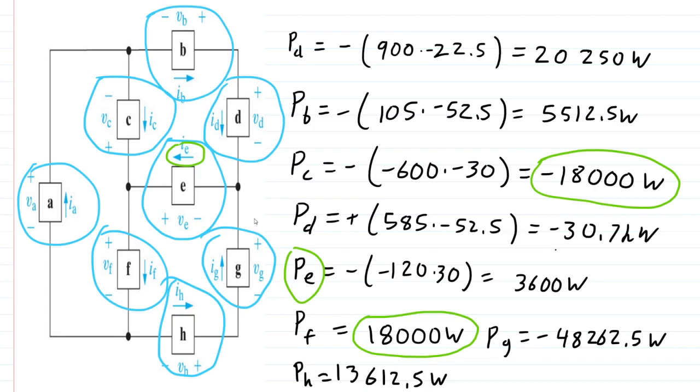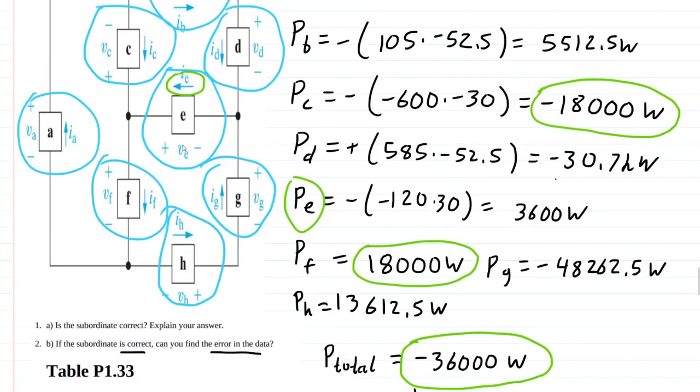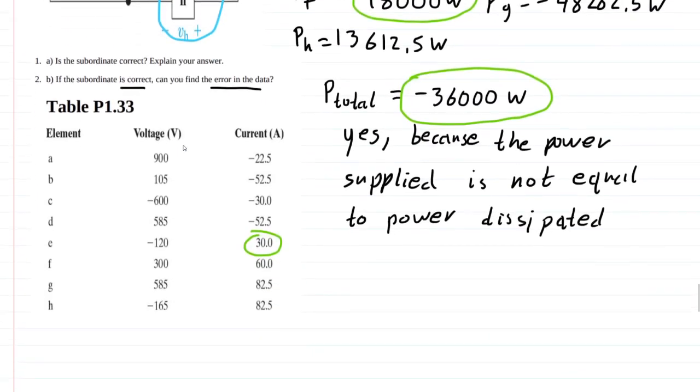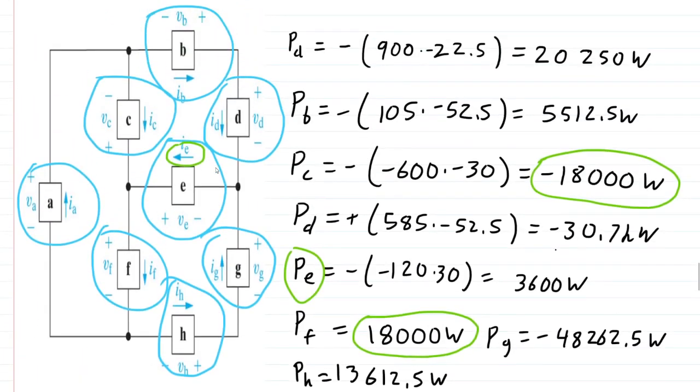You can also do a KCL here, because we have this loop here, right? So if you did the Kirchhoff circuit law analysis for all of these, you'd find out that yeah, there is a discrepancy with IE. We're going to see that IE is actually not flowing from negative to positive.